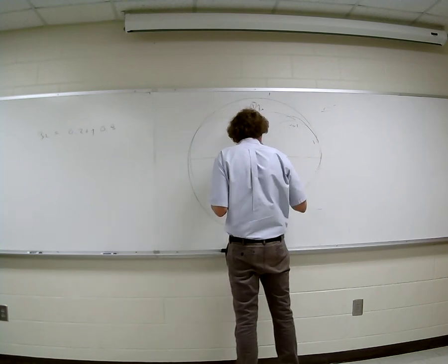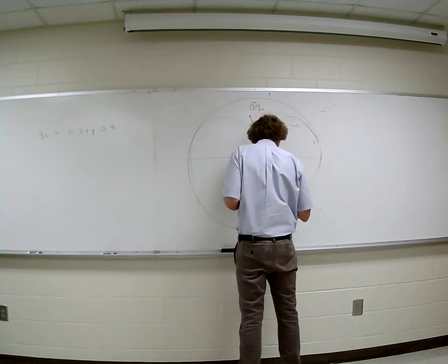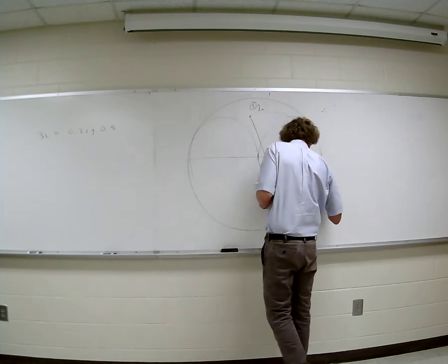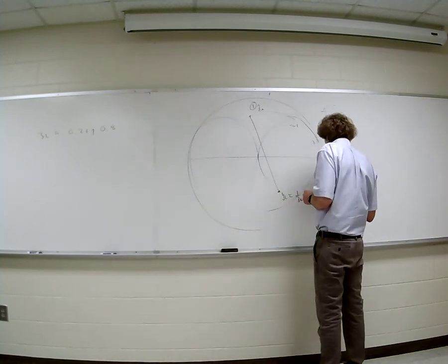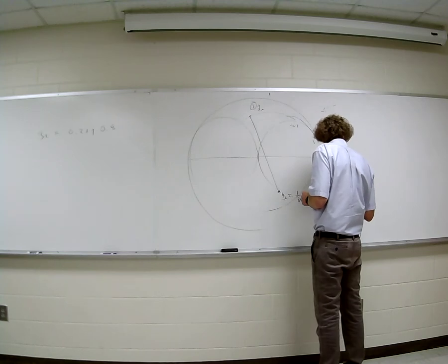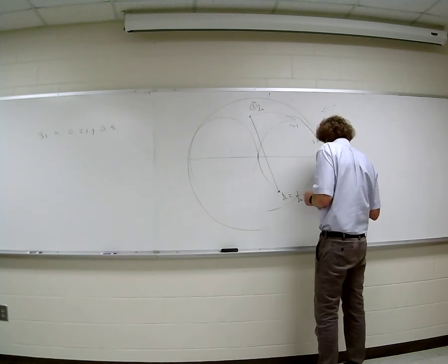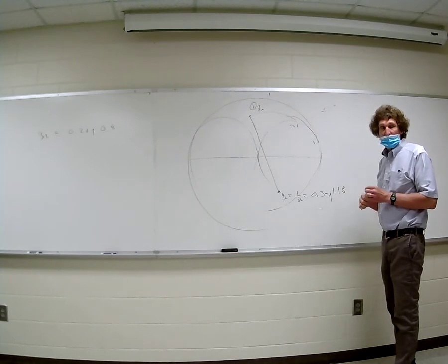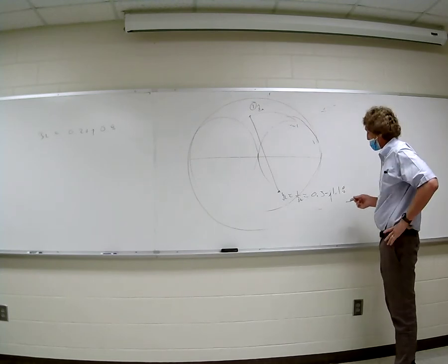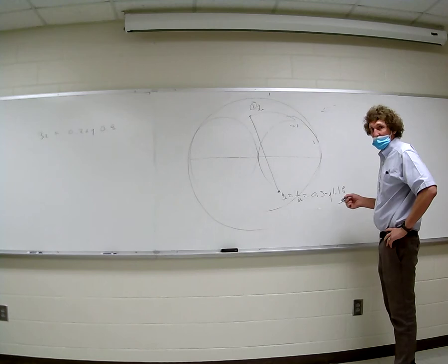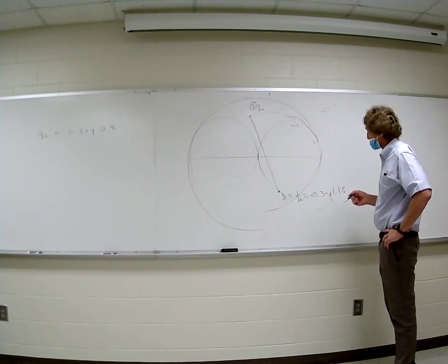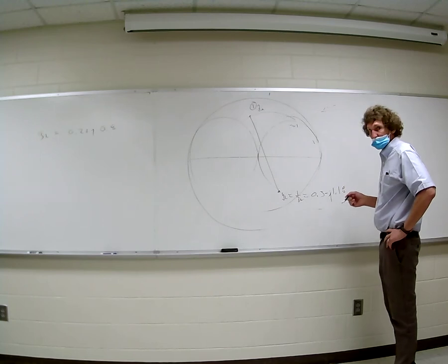and get the admittance. You're going to have to help me with this one. What is 1 over ZL here? 0.3 minus j1.18. All right. With me? Now which way do you want to go? Well, we want to go to the rim, right? So what are we going to do? You got it.